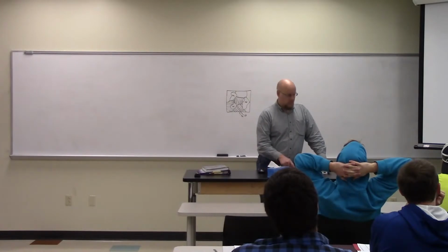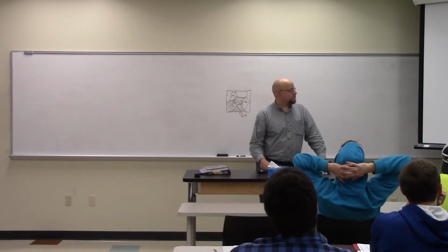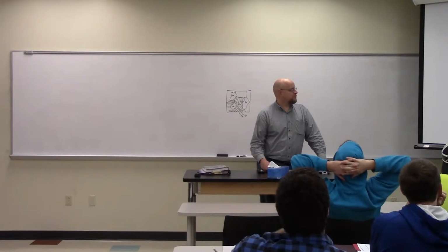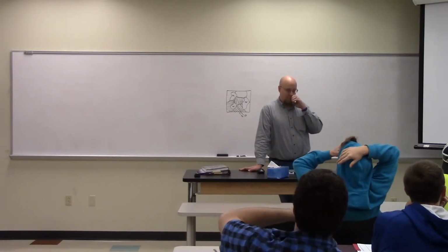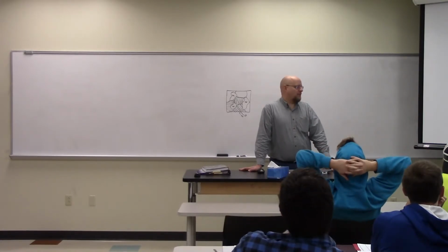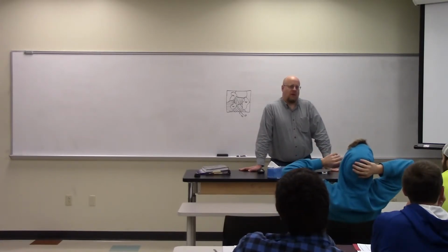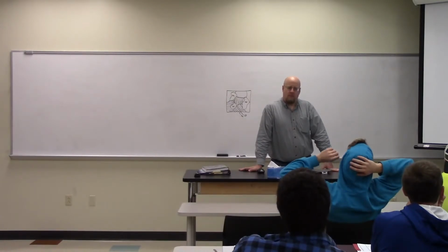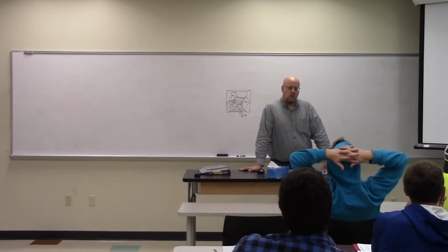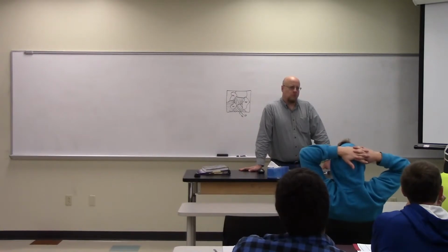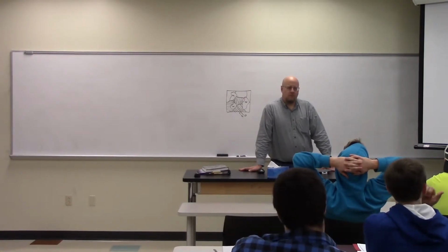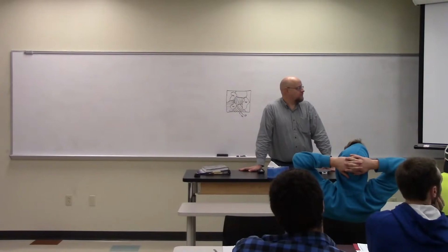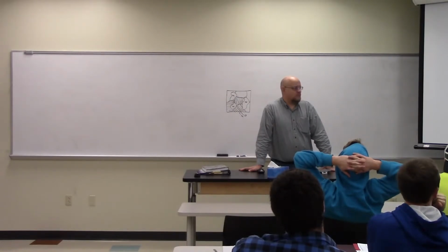Can you go back to the green one? I feel like with these ones, it isn't just a straight line over and then down. Yeah, if I give you curves on a TTT diagram, I'll make them straight lines, even though that's not realistic. So for this one, what would you tell me that is? Coarse pearlite. Right, so 100% coarse pearlite, because it crosses all the way through the 100% in the coarse pearlite category.